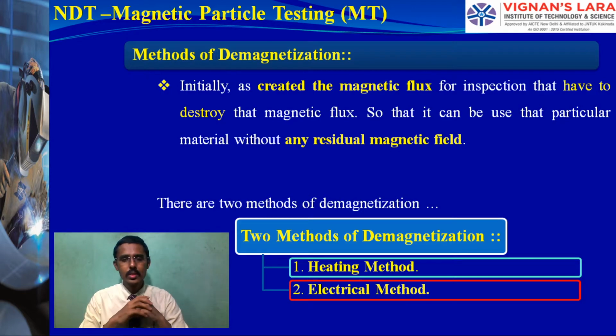As we are using a ferromagnetic material, this ferromagnetic material already has magnetizing properties, but it is not oriented. Each domain is in a various direction, and therefore we will not get a strong magnetic field. This is what we have expressed in the procedure itself. Therefore, we are using a separate magnetic field to attract all these non-oriented fields into one direction. In such a way, it will be helpful to identify the crack.